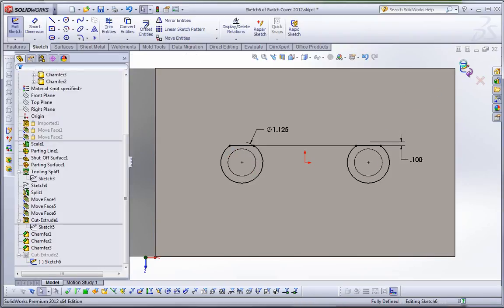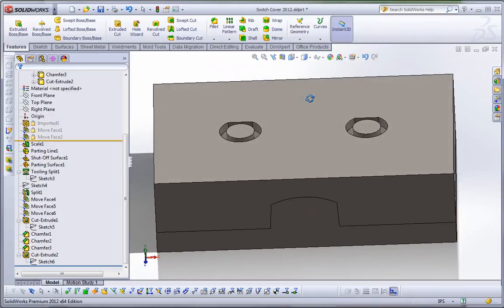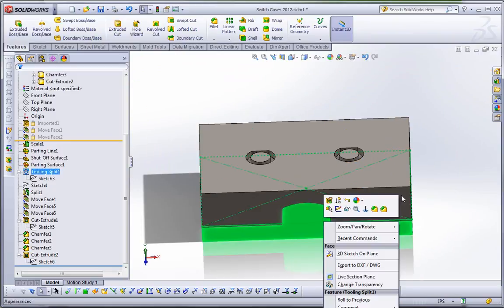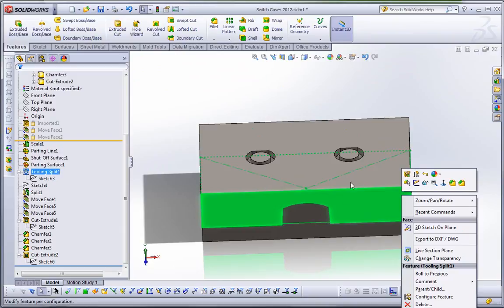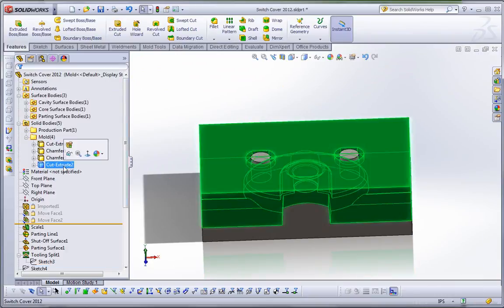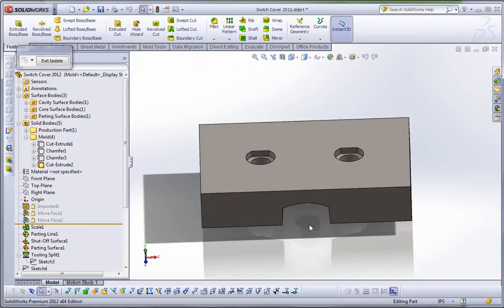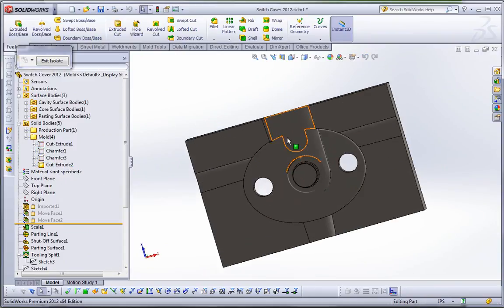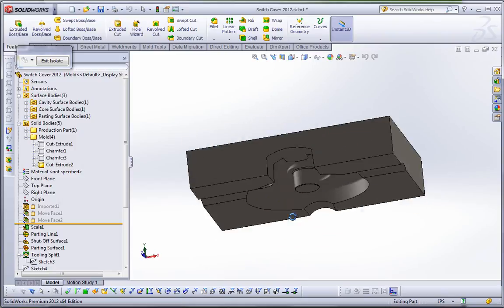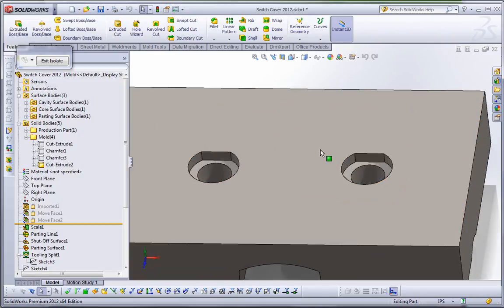So now if I come back in, you can see that I've got a pin or a pocket for a pin. Now because the inside of this, let me isolate this body. Isolate. If I rotate this, because the curvature of this inside face is such that the pins could get confused and then cause an odd shape, I need to key the inside of the pin.